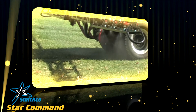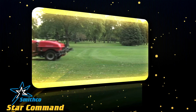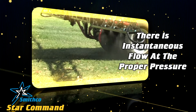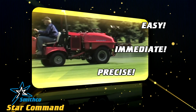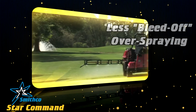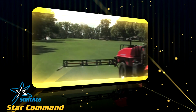Sharpshooter controls the on and off spraying function right at the tip, and shut-off is instantaneous. The liquid and pressure are retained in the boom at the tips, so when the boom is turned on, there's instantaneous flow at the proper pressure. That makes starting and ending an application pass easy, immediate, and precise. The quality opportunity amounts to less bleed-off overspraying of chemical when the boom is turned off. Likewise, there's less pressure lag underspraying that results in several feet of under-application when turning the boom on again.